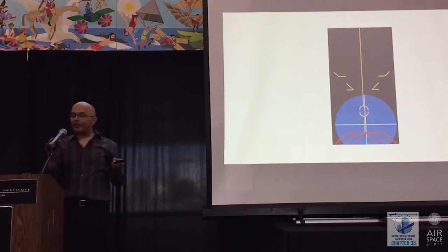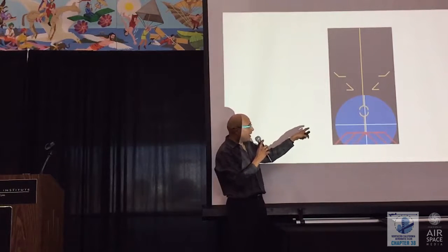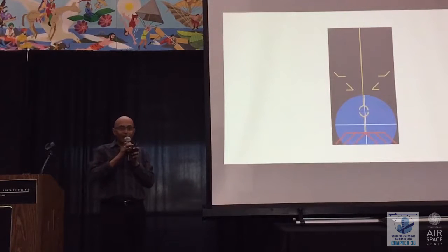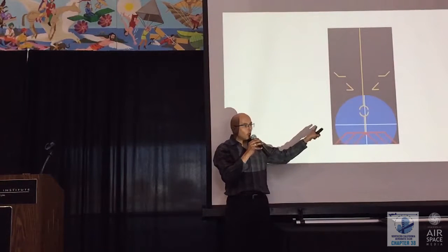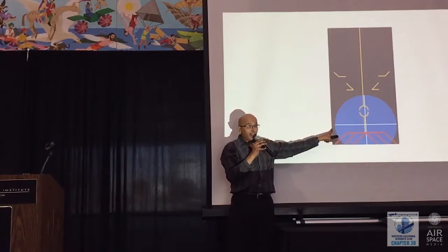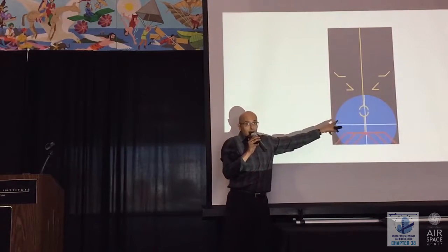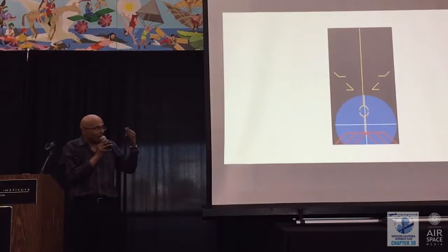And this is another kind of condition, and it demonstrates something interesting. So this is approaching an accelerated stall. Here I'm going fast, but I'm pulling a lot of G's. And what you can see here is that this tells you more than an angle of attack indicator tells you. You can see that the speed is very high, and you can also see that your angle of attack is very high. You would not be able to see this and mentally remember this picture if you were just looking at angle of attack.